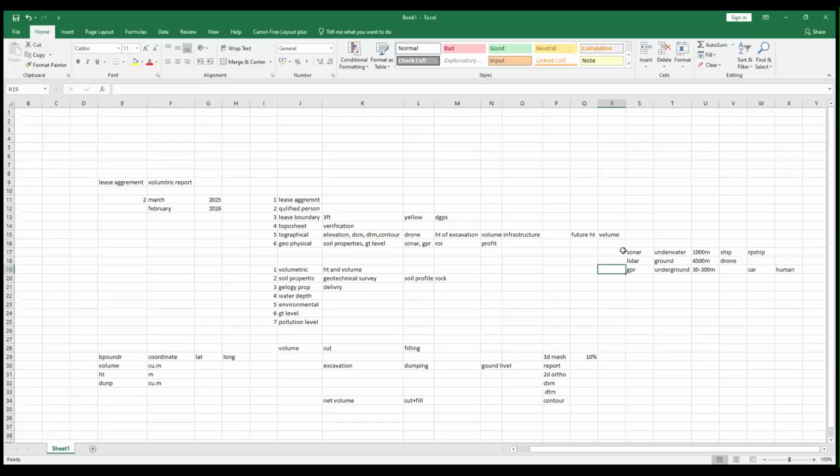or a lightweight equipment which can be carried by one person throughout the stretch, since in some areas cars will not be accessible. A person should carry it on their shoulder, so they have to walk the entire stretch, and there are properties like width and so on. So just like our LiDAR or sonar equipment, GPR also needs a proper gridding pattern. We have to design a walking grid or a vehicle grid so that our equipment travels along it and gets the data.